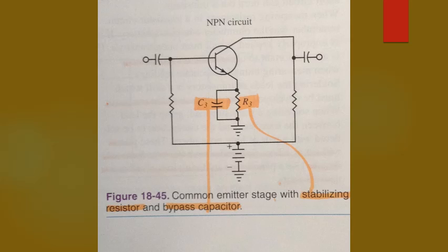There are a few methods that prevent thermal damage to a transistor. One way of reducing overheating is through the use of special circuits. See figure 18-45, the common emitter amplifier has a stabilizing resistor R3. An increase in current makes the emitter end of R3 more positive with respect to ground. The forward bias of the emitter base circuit decreases. This decrease acts as a limiter to current increase resulting from thermal runaway.